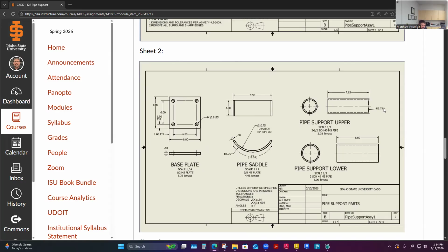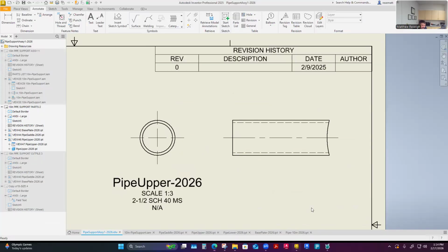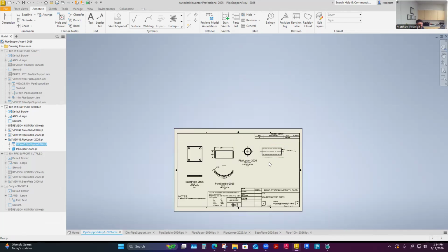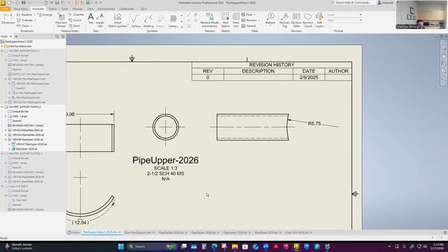Somebody was asking about this, and this is because I've used a jog dimension. So let me see what just kind of naturally comes out. Maybe it's kind of odd, but it's like a dimension of this that pushes it way out away, which is fine if you have room, right? I could actually technically drop this dimension here, and I could pull these away because this would be okay too, as long as I have room. Could pull these out. I mean, that center point of that radius is a ways out there.